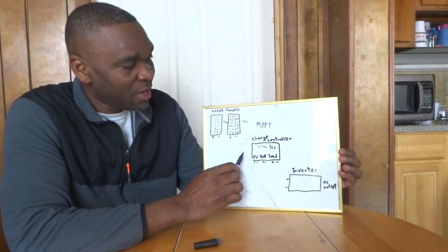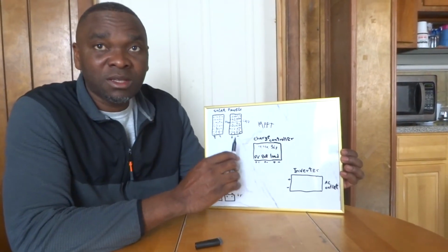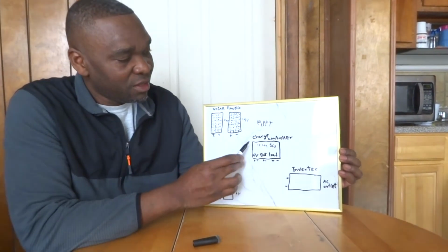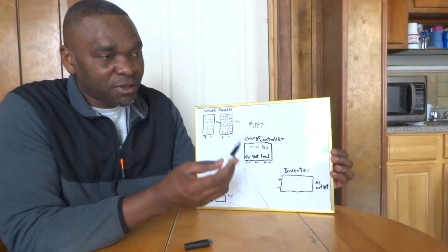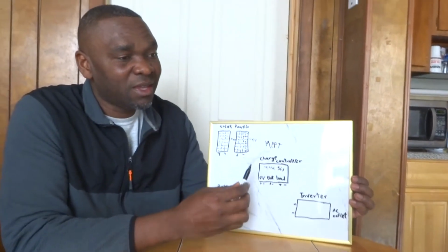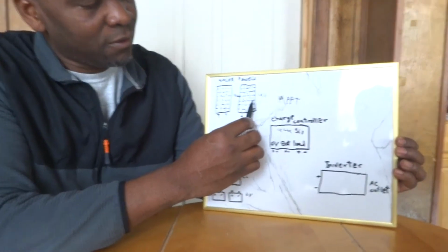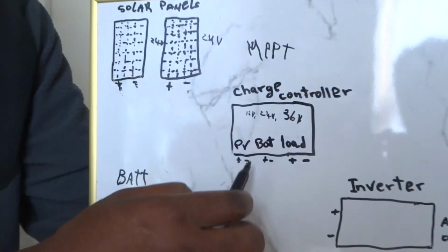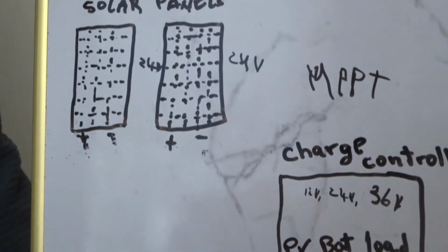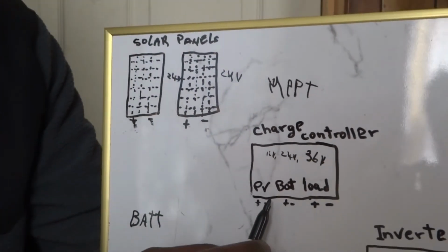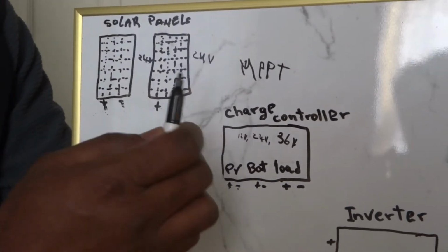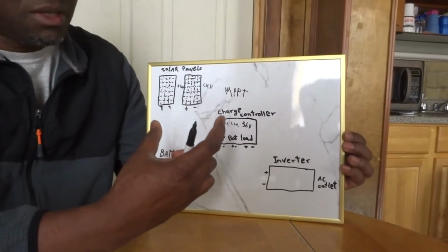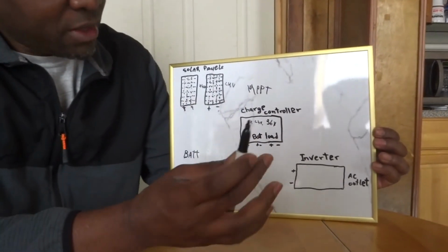Once again, for a 12 volt battery, the charge controller can still regulate the 24 volts or whatever you give it, if it's an MPPT from 48 volts to 12, but the loss will be considerable. The loss in terms of current will be high, so we don't want that anyway.